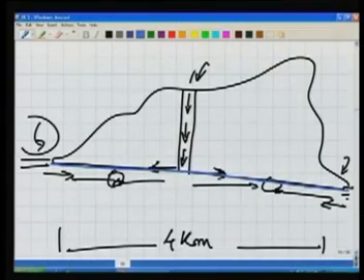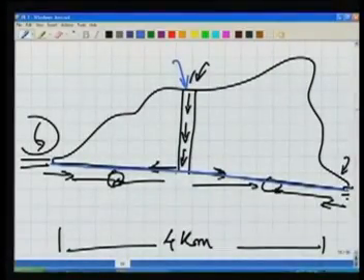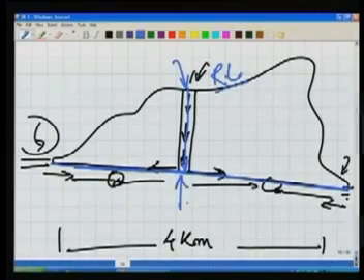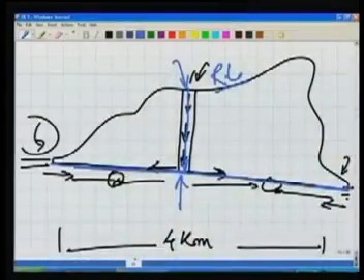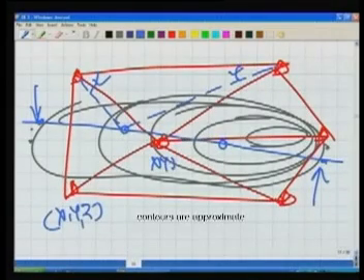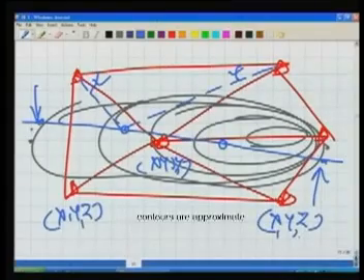So there in the laboratory itself, you are determining the RL of this point. You know the formation level, so you know the RL of the formation level everywhere. So at this point, if you come vertically down, how much down should you come from this RL so that you reach the center line of the tunnel? All these kinds of computations can be done if you have a network for which all x, y, z are known to us everywhere. So we are making use of the control network, we are making use of the triangulation for this purpose.